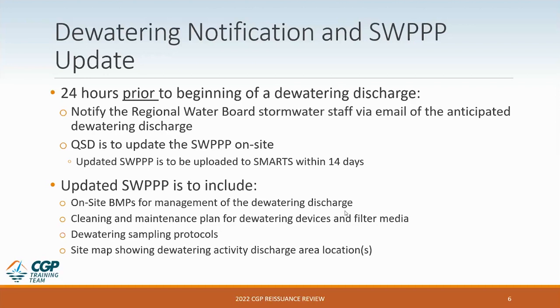Within the SWP update, you are to include on-site BMPs for management of the dewatering discharge, what your cleaning and maintenance plan will be for dewatering devices and filter media used, your dewatering sampling protocols, and a site map showing dewatering activity discharge area locations. In other words, you're going to need to make sure that you have clearly defined on there where you're going to perform the dewatering activities and discharge to.